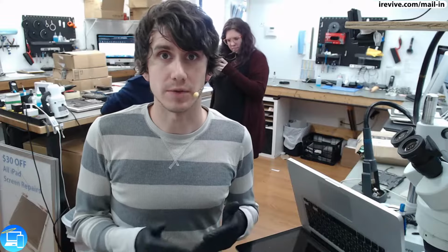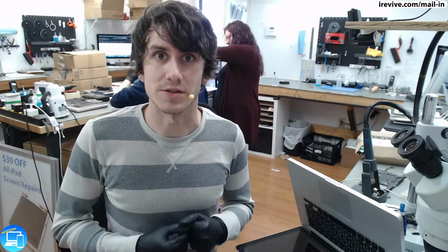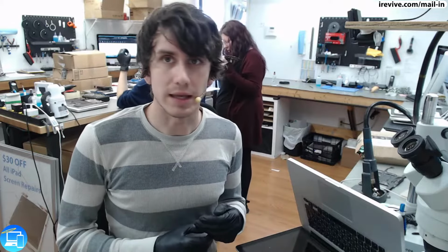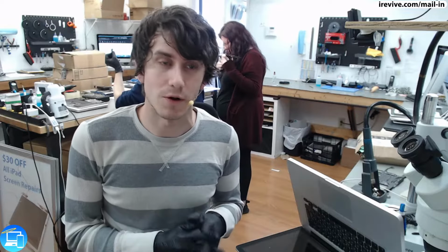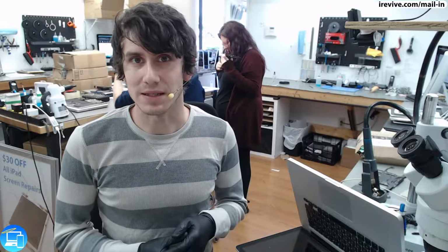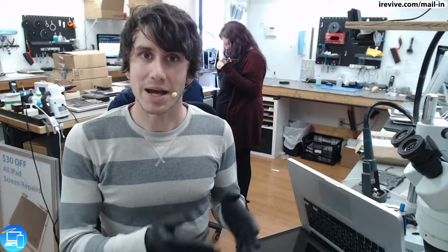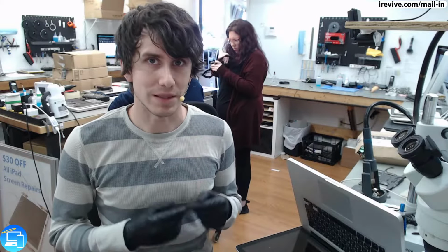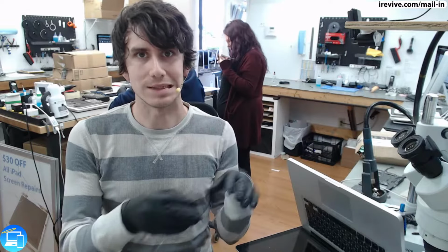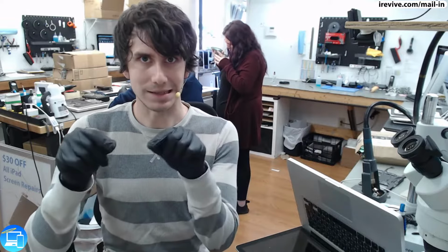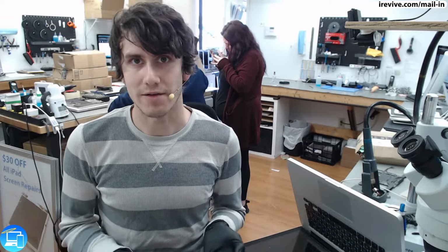All right, so today we're going to do a pretty quick repair just because we have a long list of customers today. But I wanted to do a 2011 failed GPU graphics bypass using DasDude's Gmux diagnostic tools. It's basically a graphics card patcher where we're going to reprogram the Gmux chip, which is responsible for switching between the AMD graphics card and the Intel integrated graphics.